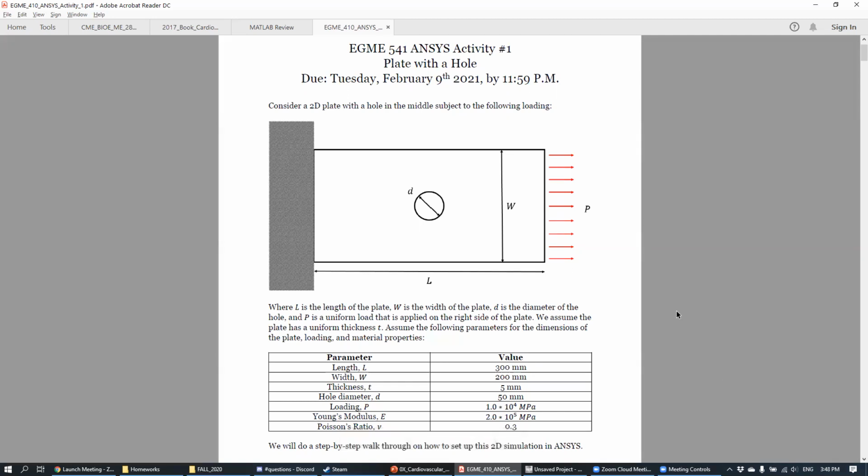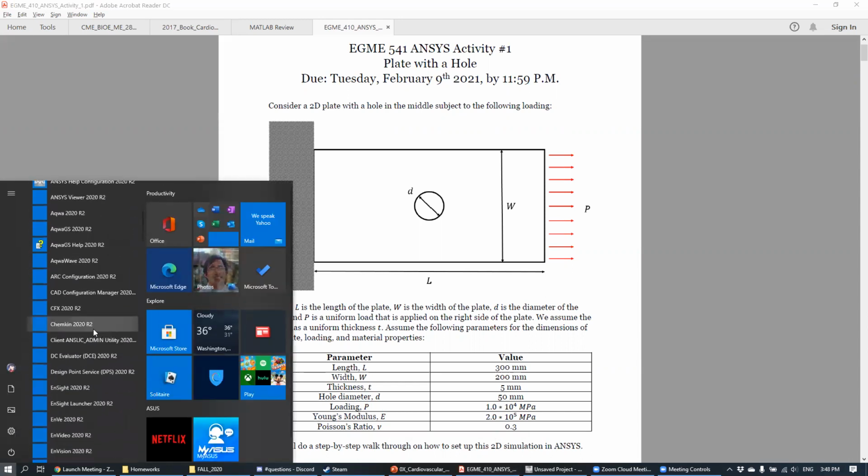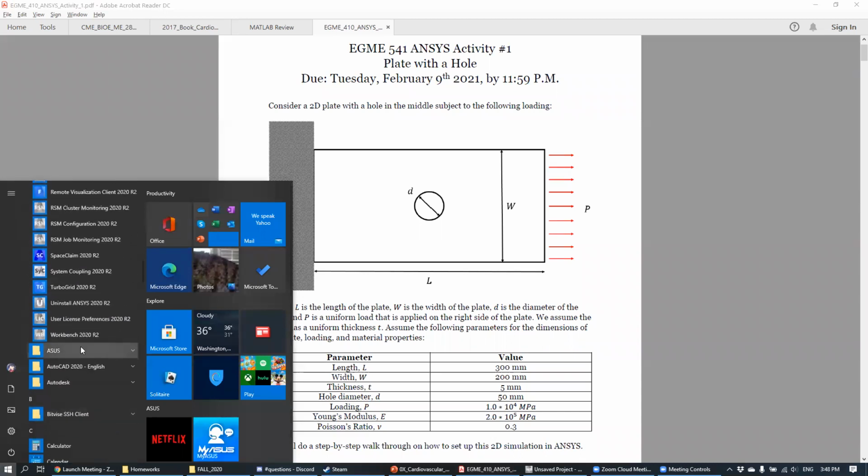So I downloaded it, correct? But I got three different ones. It says ACP 2021 and then the FinSap ICE 2021. Okay, you downloaded just the Ansys student, right? We want to use the one that's on the far right. When you download it, it should come with a lot of different packages like this. To open it, the program you want to run is called Workbench.